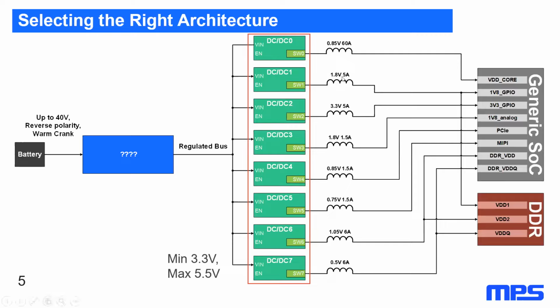The other converters, since they are quite a lower current, can be powered with regular buck converters. Typically, all these devices, the DrMOS and the buck converters for low voltage and high current, have a very low input voltage range. Usually they can tolerate about a maximum of 5.5 volts.